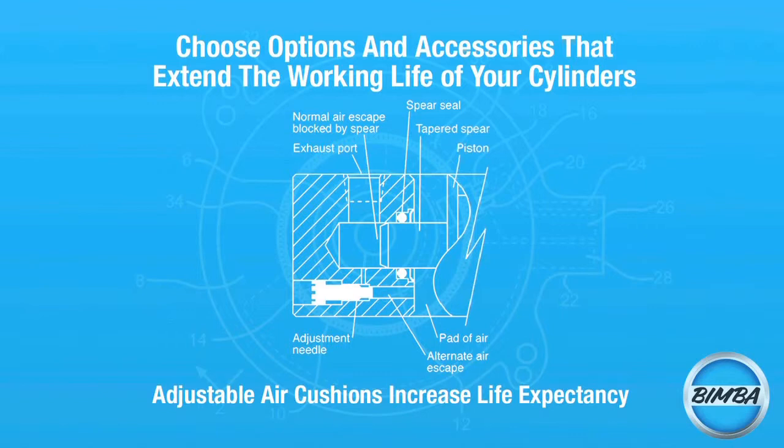Special options are offered with many spool pistons. These options are used to help reduce side loads by spreading out the distance between the rod bearing and the piston, thus reducing the effective loads at these 2 points.